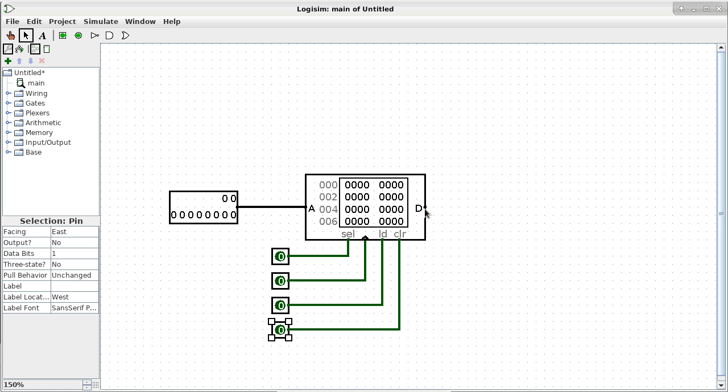Data port is the funny one, because this is one that is bidirectional. In other words, for certain operations, it is an input port. For other operations, it is an output port. So that makes it kind of tricky, okay? We'll deal with that problem later. And for now, we'll just assume that we are reading the content in RAM. So we'll have an output port associated with it. And it's complaining because the width is different. You can see how it is complaining that it should be 13 bits wide. So we'll have 13 here.